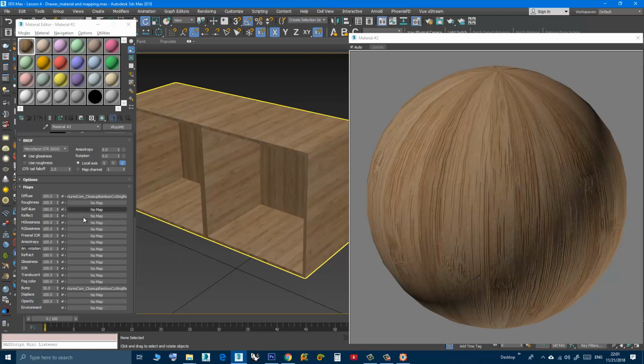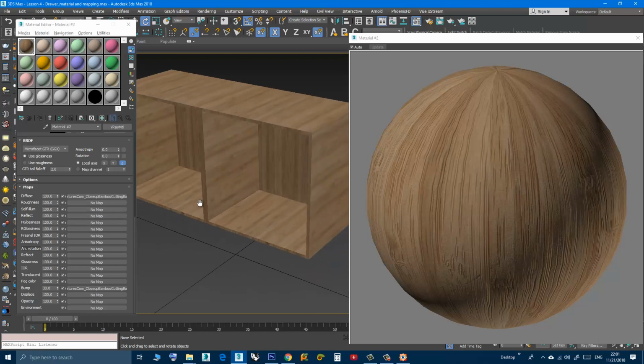All of these other textures that you add here are meant not to show directly, but to have a certain effect. When you add textures here, 3D Studio Max ignores the color information and sees them as black and white. Max cares about the contrast of these textures, the brightness of the pixels inside, to achieve certain effects.